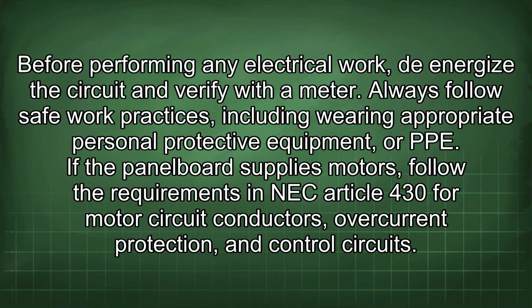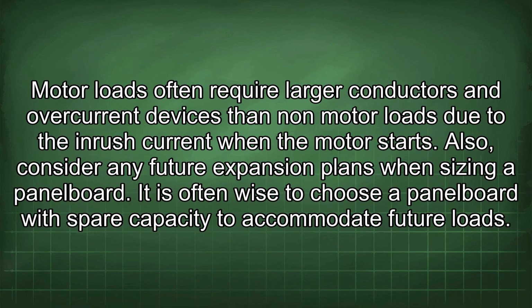If the panel board supplies motors, follow the requirements in NEC Article 430 for motor circuit conductors, overcurrent protection, and control circuits. Motor loads often require larger conductors and overcurrent devices than non-motor loads due to the inrush current when the motor starts. Also, consider any future expansion plans when sizing a panel board. It is often wise to choose a panel board with spare capacity to accommodate future loads.